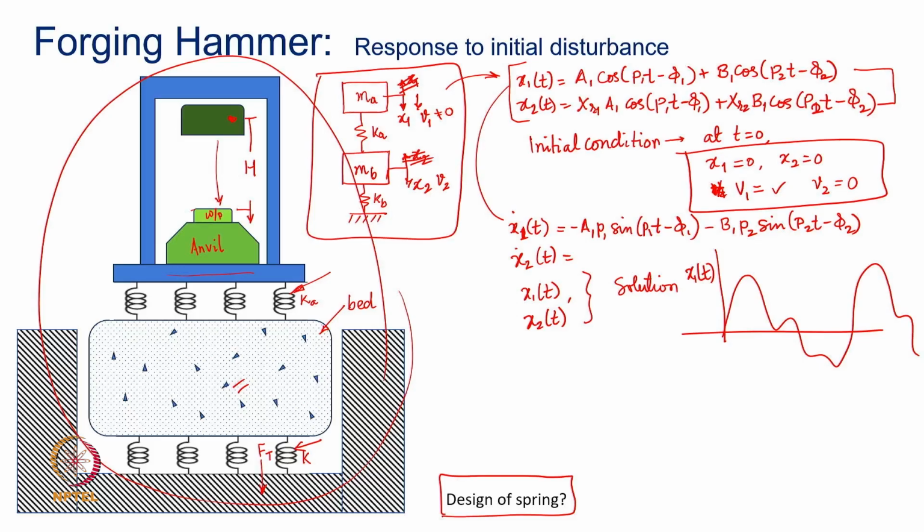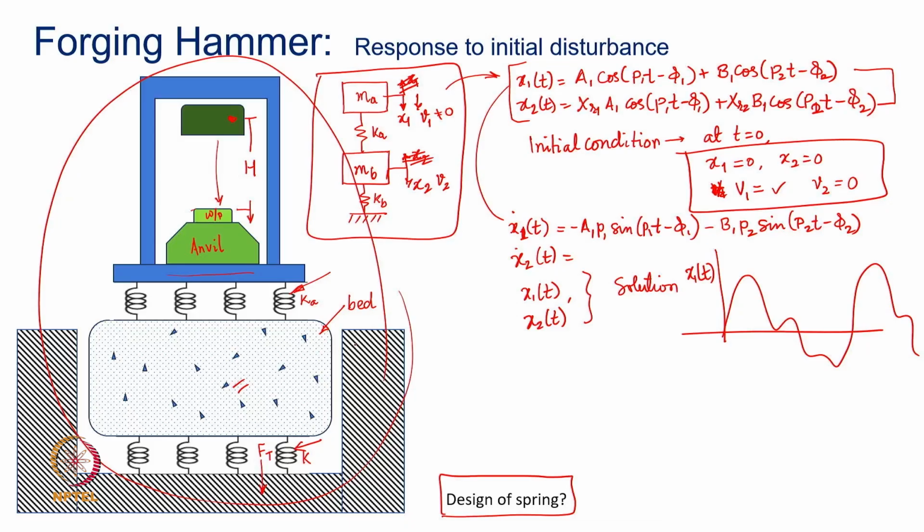Now, many times, based on your strength of material or your machine element design, you decide the spring dimensions based on a certain value of load that it takes or a certain value of spring rate that it has. But that is the reason why this vibration analysis or vibration theory is very important for you to understand. Now you are not talking about only the load. Why? Because you can imagine that both of these masses are moving independently, x1 and x2 will have their own motion, right?